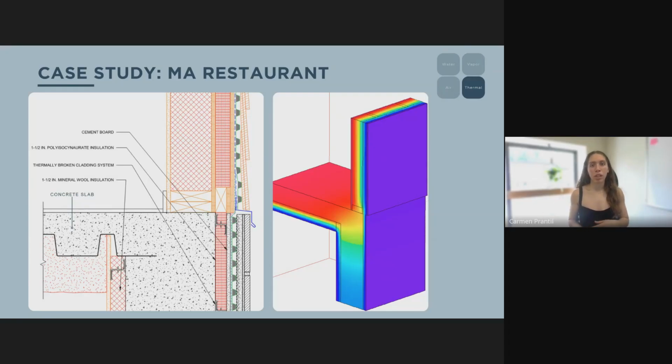So we used tools like thermal modeling to gauge the thermal bridging impact at several key details early during the design, one of them being this basic wall detail, which you see here. So this first option, we put split insulation in the wall assembly here. So we've got the exterior insulation, the interior, and the studs. We carry that insulation down the exterior of that below-grade concrete wall.